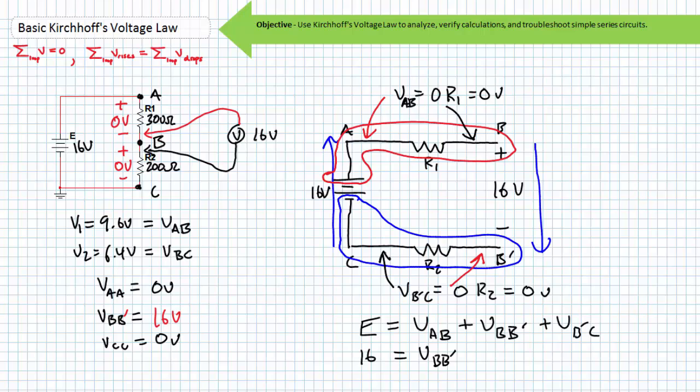Recall that the largest voltage drop in a series relationship always occurs across the largest resistor in that path. The resistance of an open circuit is infinite, and it can't get much larger than infinite. Therefore, all voltage will be dropped across this infinitely large resistor. Pause to consider opens at nodes A or node C. In both scenarios, no voltage drop will occur across R1 or R2 because no current will flow through either element.